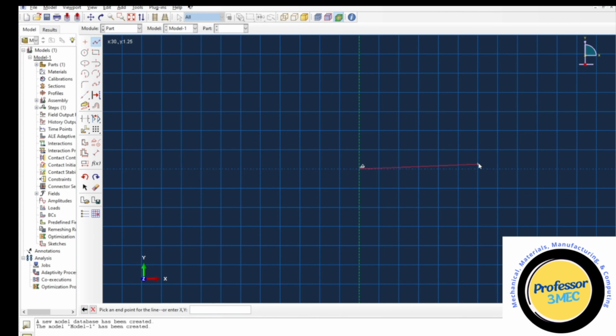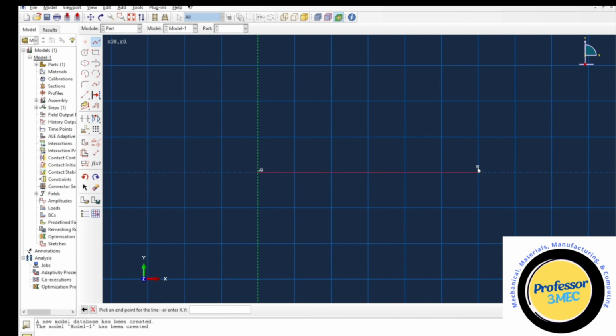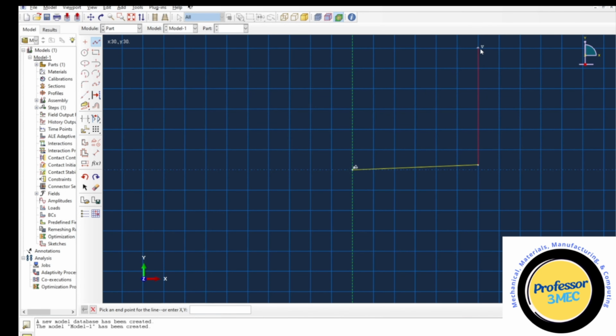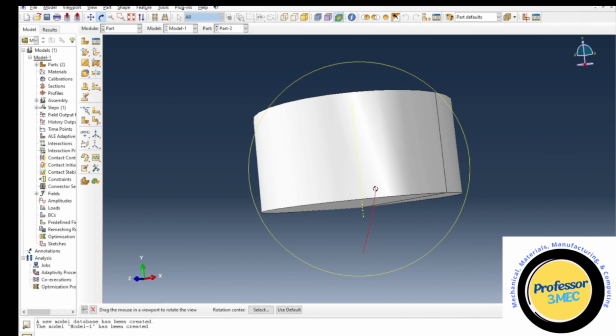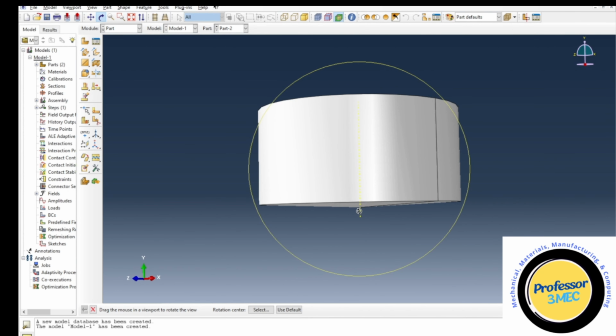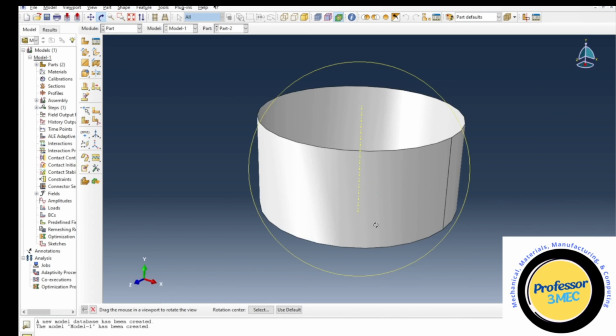So I'm just going with a certain angle to have that kind of conical shape as we need. Again, this is just approximate geometry I'm making. So I will just press done, and then it will revolve when I have the shape of the die. A small conical shape. I don't know if this is enough or not. Let's see how it looks.